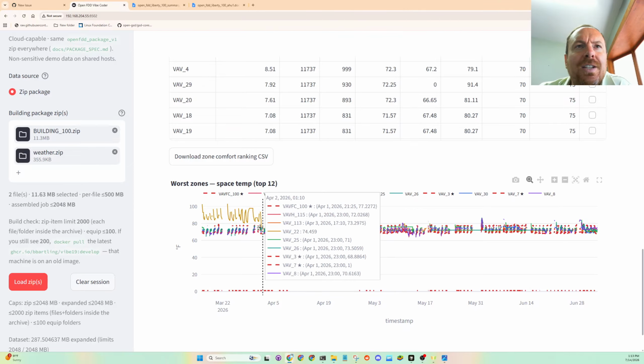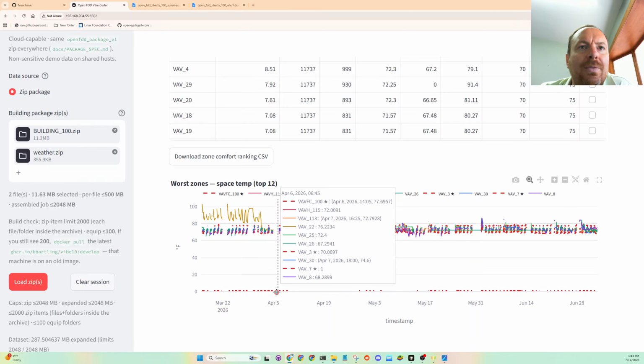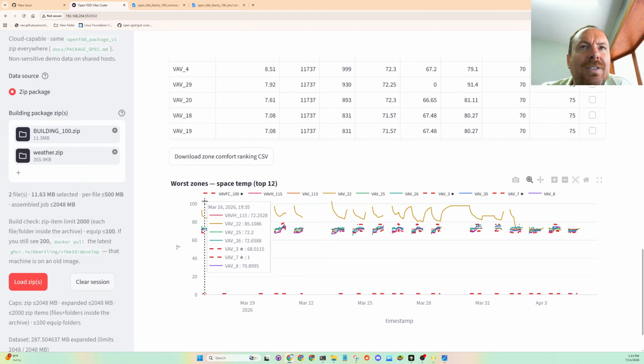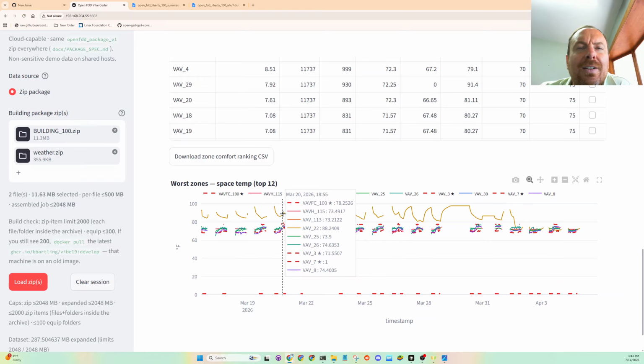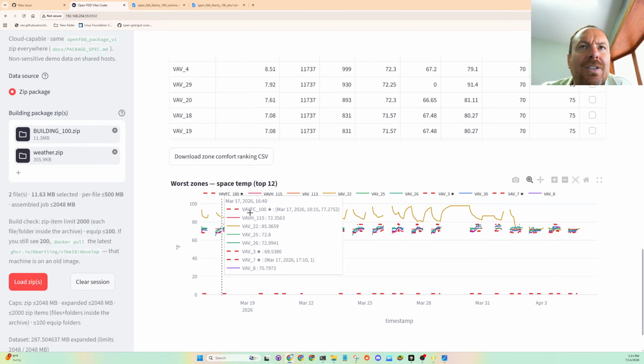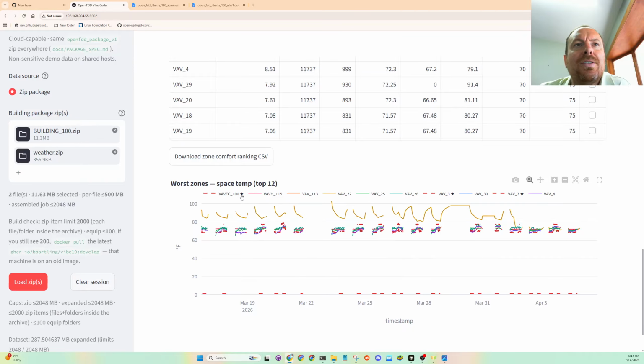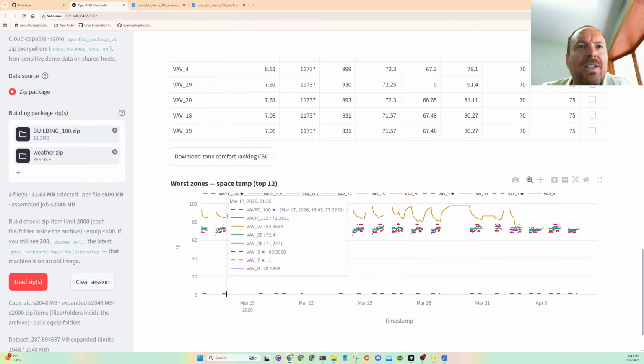So this data is filtered for when the building is occupied, and there is something going on that's all squirrely. Like look at this VAV box that continuously reads 100 degrees. Wow, VAV 22, 100, something's going on with that one. And if you see the ones with little stars, these are the ones that are outliers too, flagged by this z-score thing.